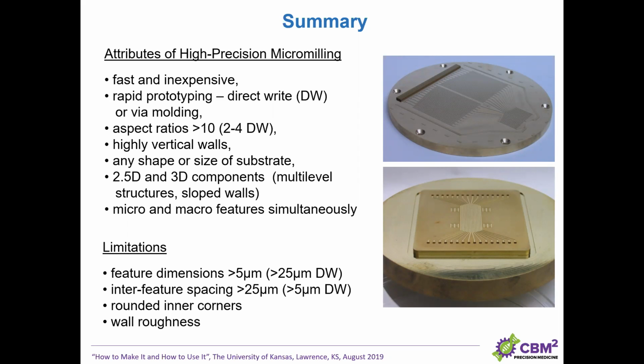Limitations: feature dimensions higher than 5 micrometers. Definitely, that's probably already pushing it for milling. Inner feature spacing, as I said, is limited by the tool, about 25 micrometers, rounded inner corners, and the wall roughness.